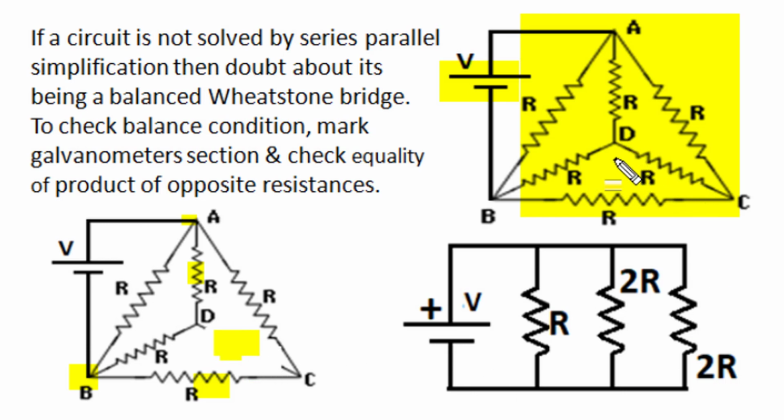Current in the DC branch, or in this resistance, will become 0, and in the remaining circuit, this R and this R, this R and this R become in series, 2R. Similarly, this R and that R become 2R, and now in this resistance R, directly V voltage is applied, so its current is V by R. In these two resistances, current is V by 2R, and similarly here also current is V by 2R.